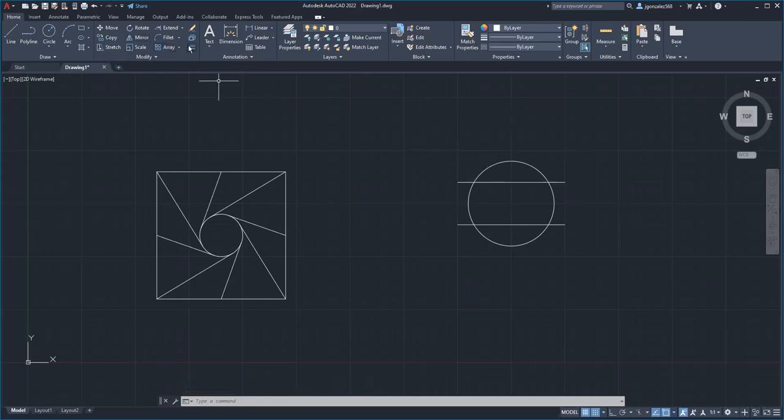It's a little easier to see when you do it on circles. Let's try it. Let's do offset again just for fun. I'm going to delete these circles when I'm done because that's not part of the example. But click offset, choose the circle. Well, actually, it wants my distance. Let's pick 0.5, right?